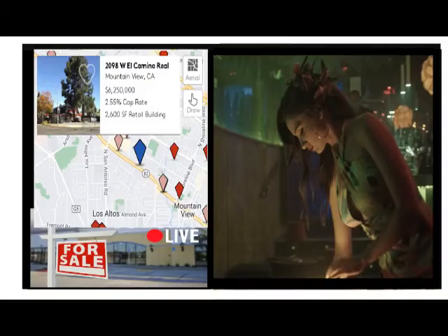Wiring in the average house also should be able to carry at least 100 amps of electricity at the required voltage. Because of the steadily increasing number of household appliances, many contractors recommend a minimum of 150 amps.